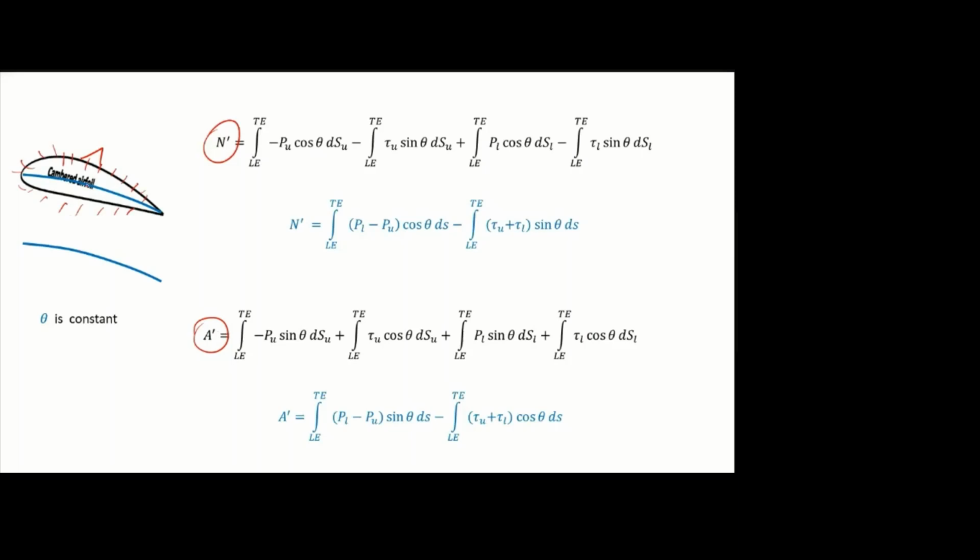So we are going to assume the aerofoil is very thin so that the upper surface and lower surface coincide on this camber line. So what we finally take is only this camber line, okay, in aerodynamics 1. So whatever results we are getting in this aerodynamics 1, it won't be accurate. It just gives you some initial idea, just approximation methods.